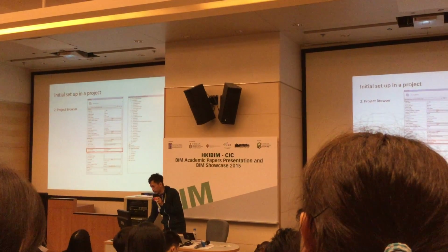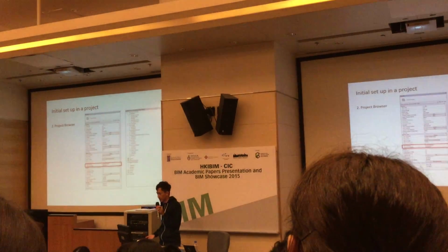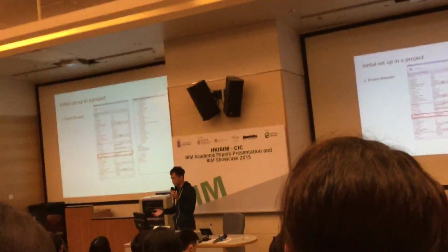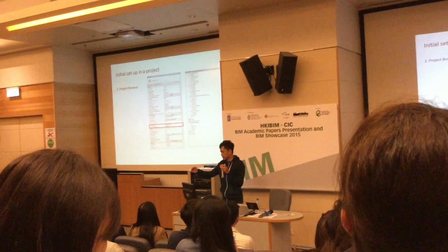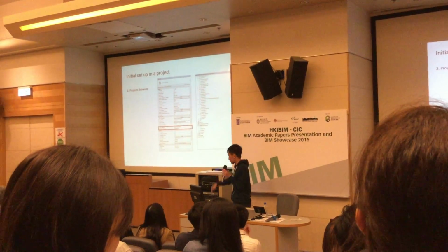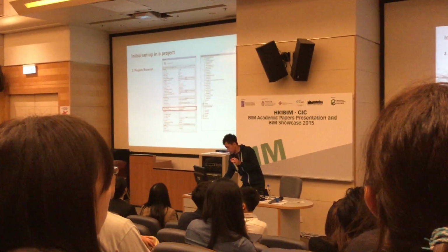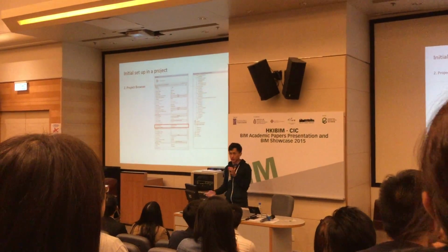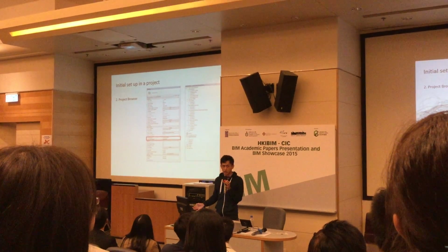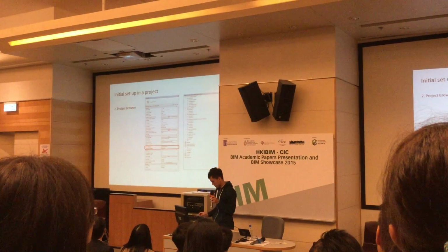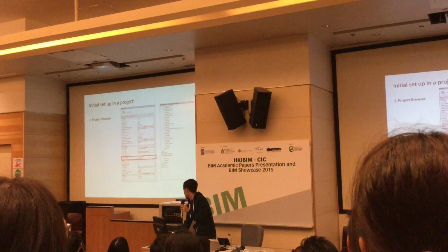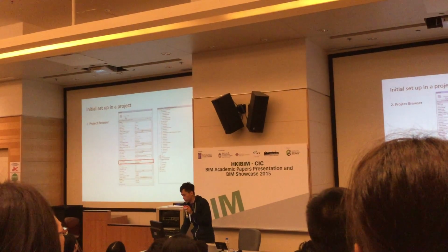And then I go to plan view, and after that I check what I draw on the plan view in a 3D environment, and so on. So basically from 01 down to 09. 09 is an export to Navisworks for clash analysis or coordination during design team meetings. And the red box is basically what I defined there, and you can see it in the properties bar.